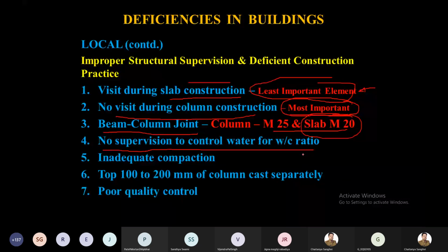So what is happening, like a contractor is there, and the contractor finds that the workability is very less, then he will give the sign to pour more water, and the operator will put one more bucket of water. Now we know that if the water cement ratio increases, strength degradation takes place, but we are not observing that part. When the next concrete batch comes, we say, okay, now good workability is available, but that workability we have compromised with the increased water cement ratio.